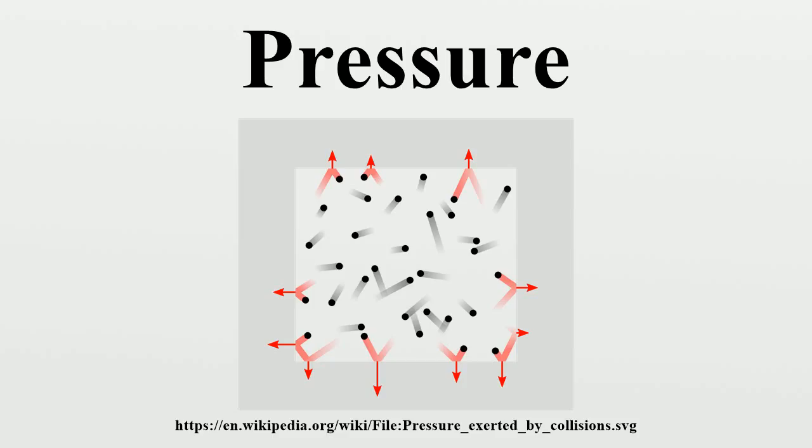Gauge pressure is the relevant measure of pressure wherever one is interested in the stress on storage vessels and the plumbing components of fluidics systems. However, whenever equation of state properties, such as densities or changes in densities, must be calculated, pressures must be expressed in terms of their absolute values.